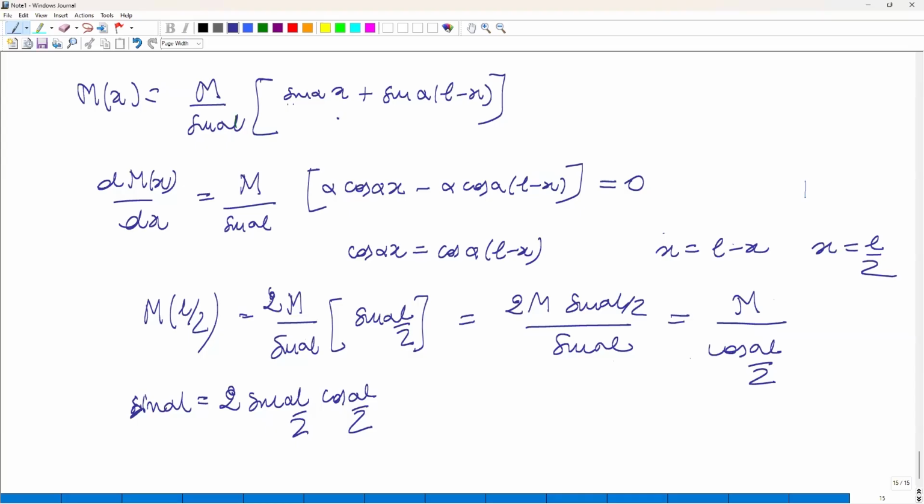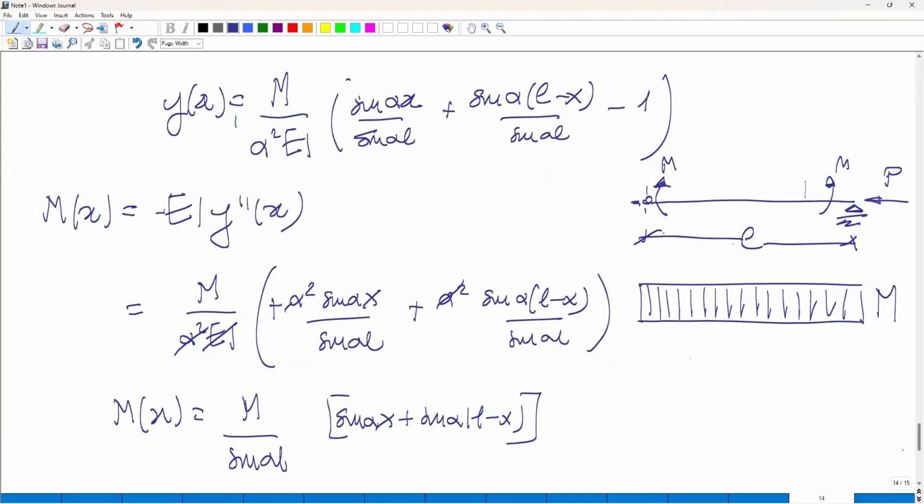So if you want to draw, this is a parametric function, actually, it depends on alpha. If we go back to our diagram of bending moment, it means that our diagram of bending moment will do something like this for increasing alpha, always at mid-span. So designing, neglecting these second-order effects of the axial force, in this case, cannot be safe. Because if you neglect them, you will design for a bending moment which is always lower than the true one, because the axial force has an amplifying effect.